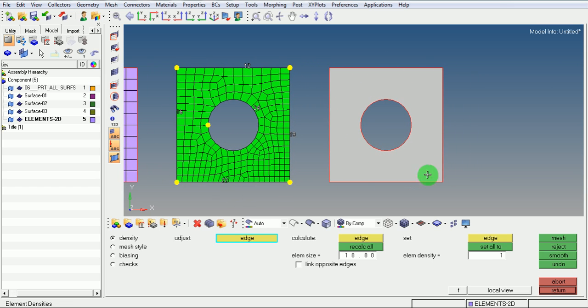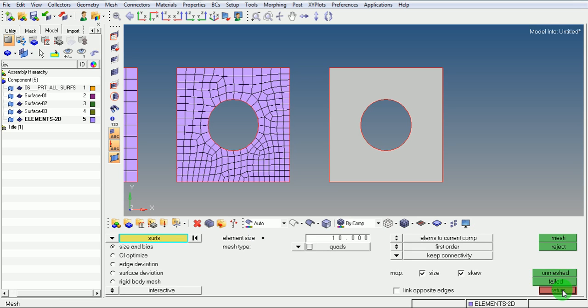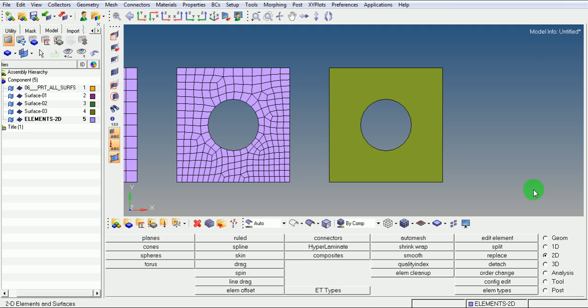On this surface, I will show you how to do a systematic mesh. Pick on return. Come out of the meshing command or the meshing window. First of all, I want to capture the hole. To capture the hole, we need to put a washer around this circular hole. That will come in the quick edit option F11.